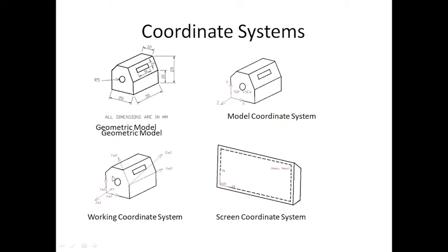So what we do basically is, every geometric model will have a common reference, just like this one. This is 0 0 0 with respect to this. All the features or entities of this part are referenced. And here, when you are generating this sketch, you are temporarily referring to this edge and this edge so that you can properly locate this.